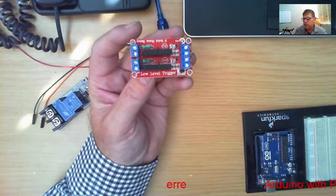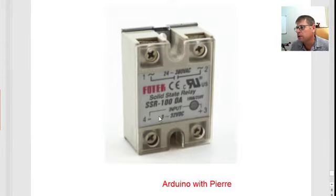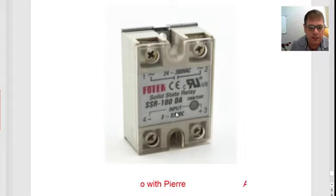Right, let me show you another type of solid state relay. This solid state relay, you can see, is a heavy duty one, 100 amps. So the AC voltage on this side that can be switched is from 24 to 380 volt AC, alternating current. Your input DC voltage on this side to initiate this switch is between 3 and 32 volt DC. So this is a heavy duty solid state relay that you can use to switch AC loads.